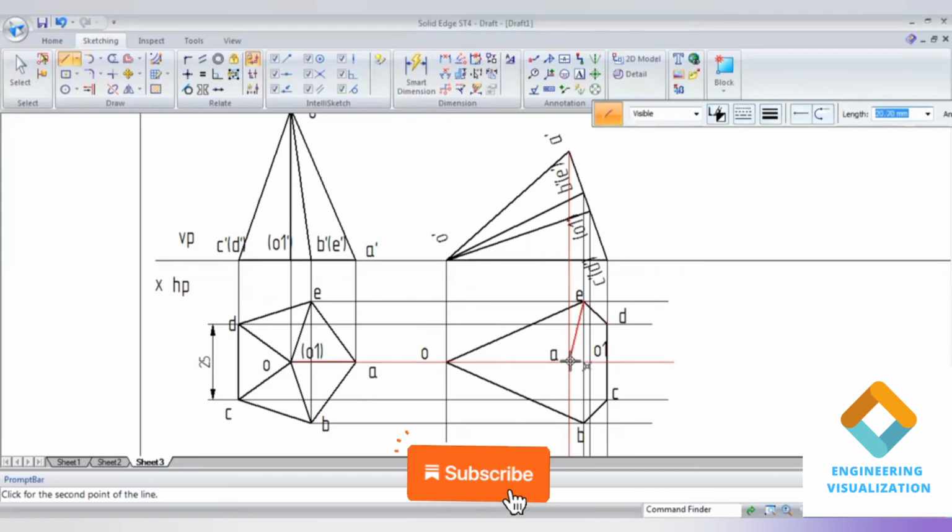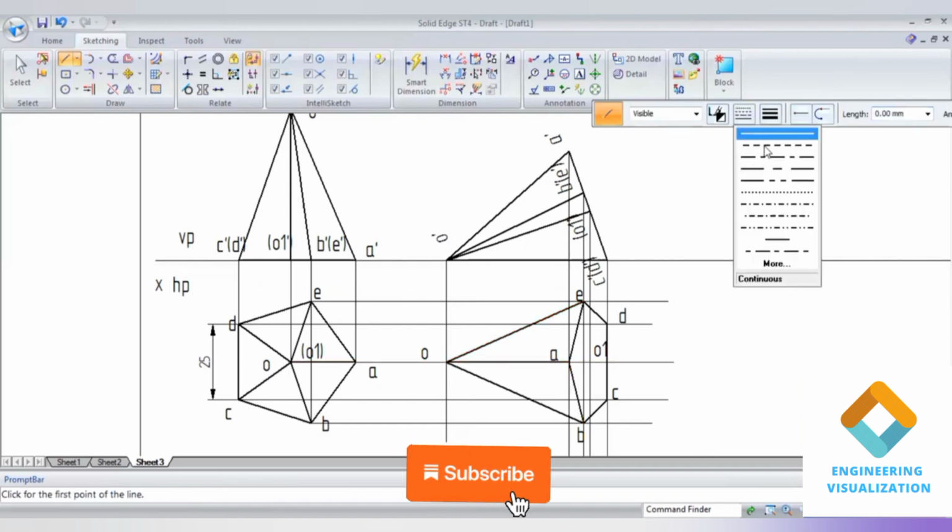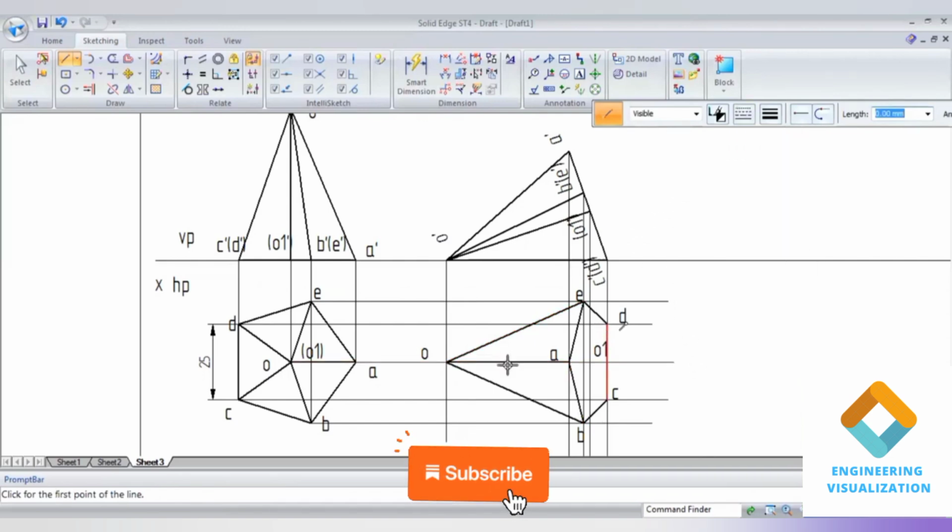Here from the top face, the pentagon is visible, that's why it is continuous, and A dash 2 is also continuous. But the triangular face D, O and C is not visible, so it is drawn with a dashed line. And the axis you have to show.